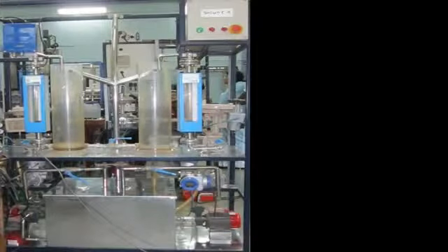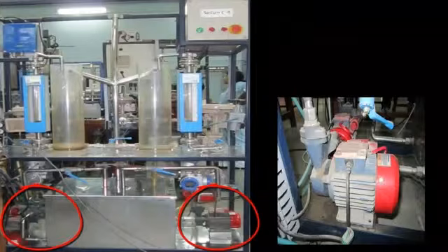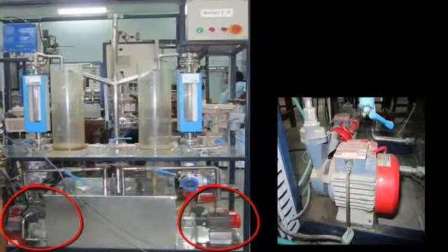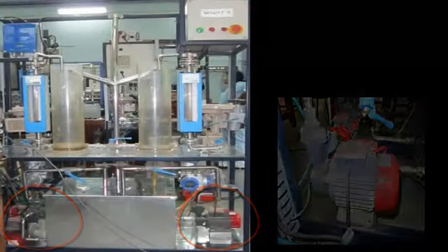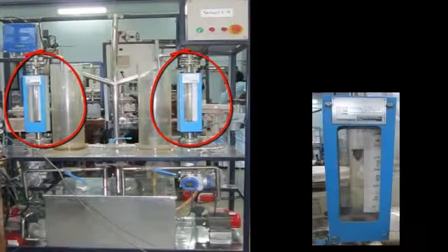Let us now take a look at the setup that you will be using. On the top right hand corner is the power box and the controller knobs for the system. There are two pumps which pressurize water, and the flow of water into the tanks is controlled by the pneumatic control valves, which we will be looking at later. Next, we have two flow meters which measure the flow rates for the disturbance and the manipulated variables. The flow meters are of the rotameter type, and they belong to a class of meters called variable area meters, which measure the flow rate by allowing the cross-sectional area the fluid travels to vary, causing some measurable effect measured by the instrument.